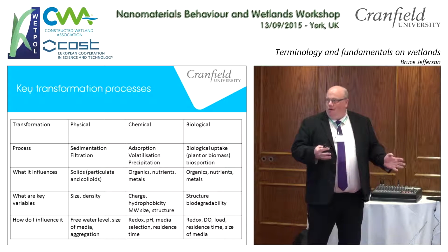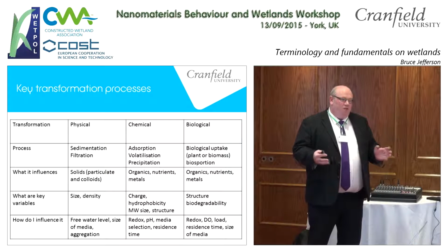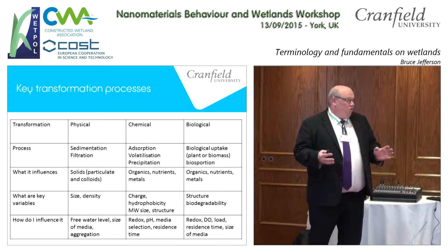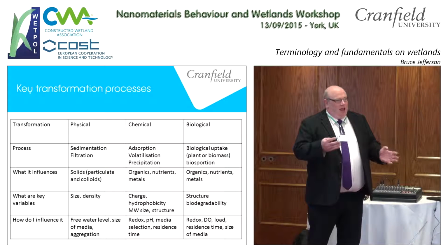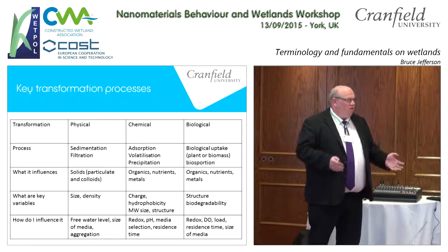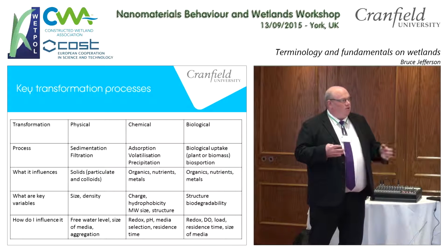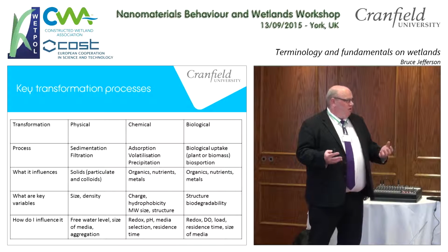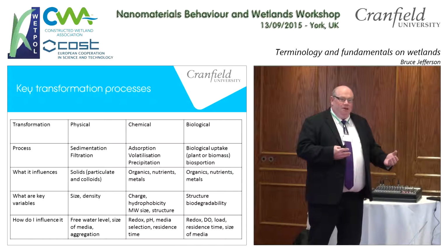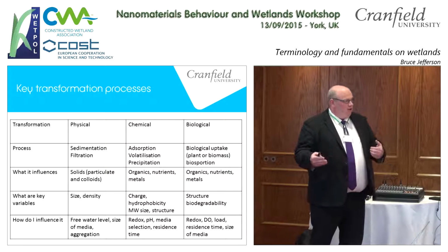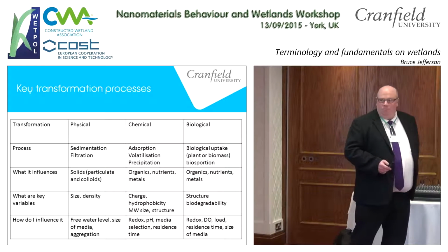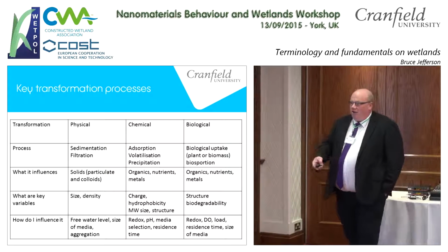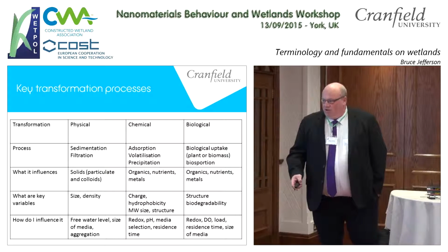In our traditional wetlands that tend to be subsurface flow, certainly in the UK, they will be oxygen starved, so will be anoxic or anaerobic. And then if we go to the vertical flow systems that are used for total sewage treatment, we're going aerobic. So we've got a whole range of redox chemistries that could be going on, and biological consortia that could exist in these systems, depending on what I'm trying to use them for. That then gives me a range of ways of trying to change things.